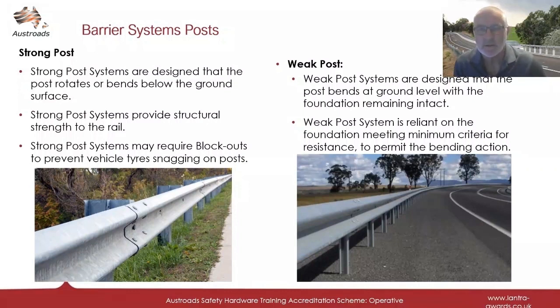Weak posts. A weak post system is designed so that the post bends at ground level with the foundation remaining intact. A weak post system is reliant on the foundation meeting minimum criteria for resistance to permit the bending action.